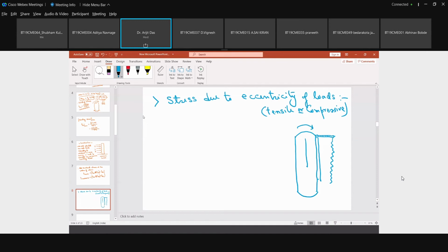Again, there is a pipe or a reboiler, so it will try to bend it in this direction. So there are some eccentric loads essentially, and they individually try to bend it in their resulting direction. So that's why we have to consider these eccentric loads also. It is very easy for the calculations. What is the eccentricity?